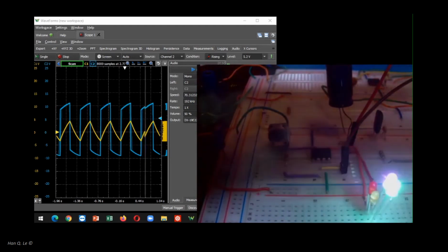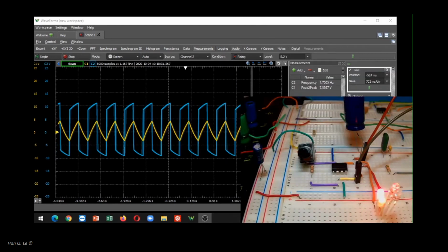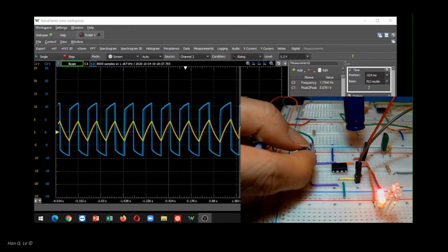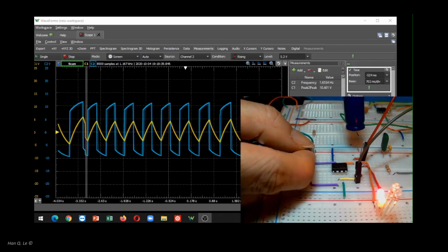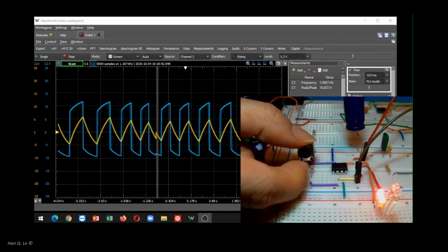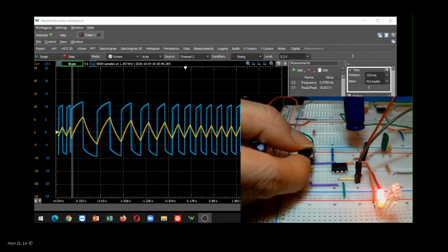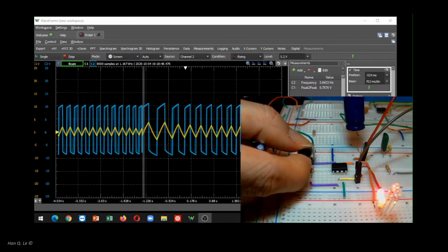If the frequency is being chirped, the frequency measurement by AD2 scope is not accurate. Hence, allow sufficient time for the frequency measurement to settle before taking data. Observe that even with a small tuning change, it took seconds for the frequency values to gradually and asymptotically approach its constant values.